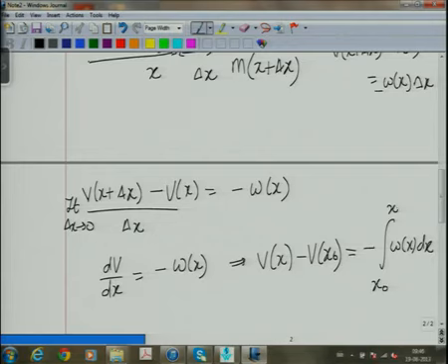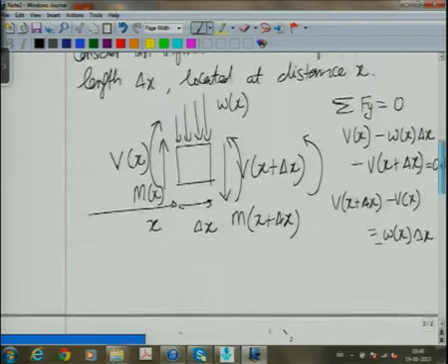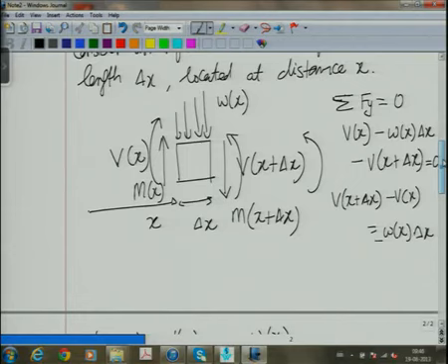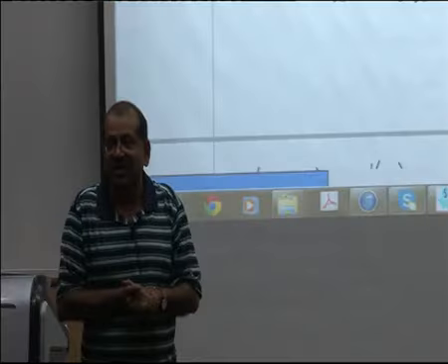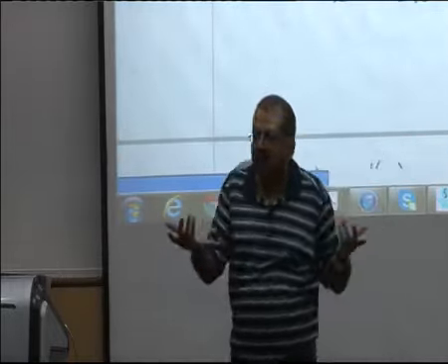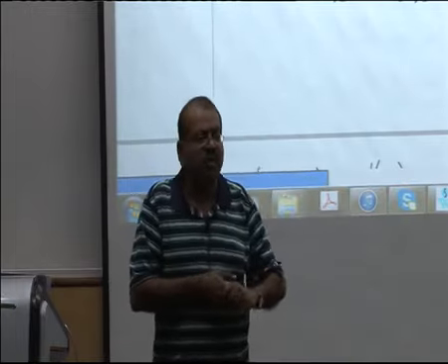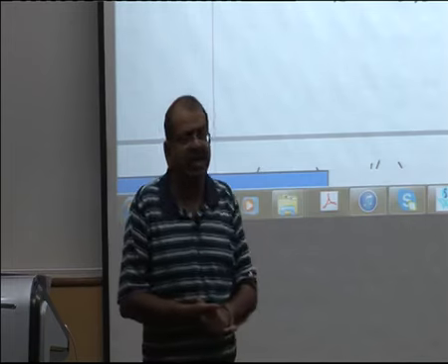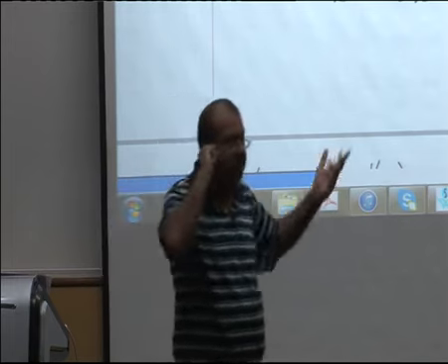Okay. So now we do the same thing for the moment. When I do the same thing for the moment, I will again take all the clockwise moments. So I will get, what will I get? M of x plus delta x minus M of x. Now before I write the moments, first I should define the point about which I am taking the moments. I can either take the moments about the left edge or the right edge or about the center, anywhere I could take. What should I do? Let's choose the right edge. It won't make a difference, I can choose any point.